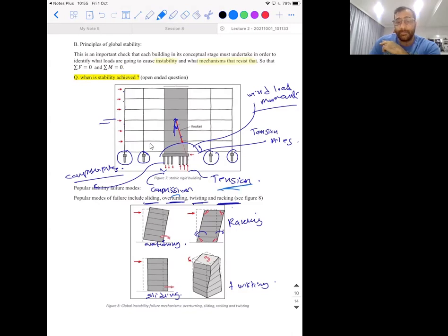This is important because you have to design the building to withstand all of these. So you hit it with the wind this way, then you hit it with the wind that way. You hit the wind from the windward direction, and then from the back. All of these piles should be able to withstand tension and compression. So when you're thinking, okay, this will cause compression, what's the mitigating or the stability providing elements? Oh, these that are placed in tension. They'll maintain equilibrium. Same when you reverse. There's a seat belt for compression, and that's the tension here.